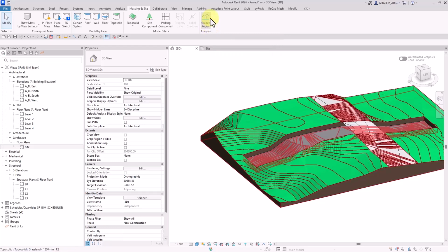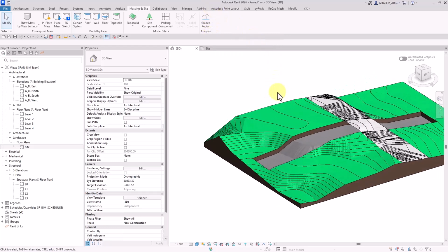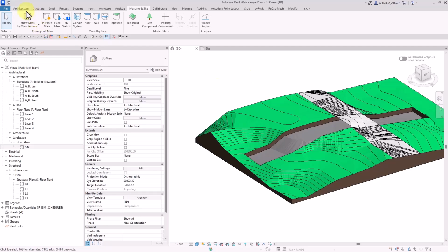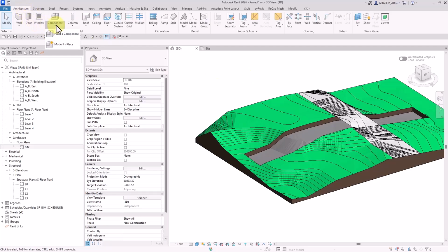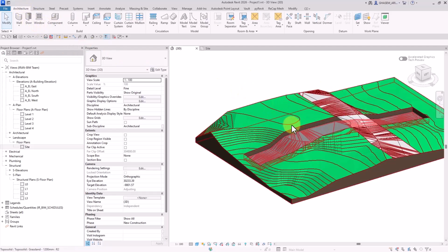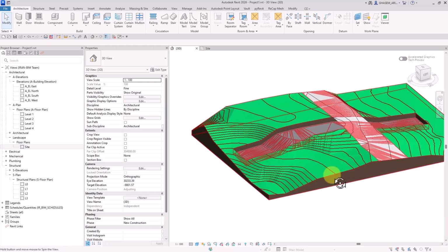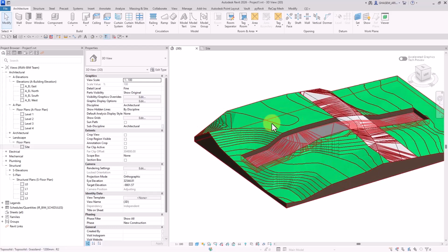Oh, and guys, now that I said problem, we also had another problem in previous versions of Revit in Toposolids, when we were using voids for creating cuts in the topographies. The void command wasn't really working if we had a complex topography. We weren't able to set a cut.